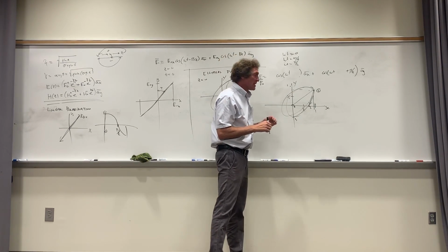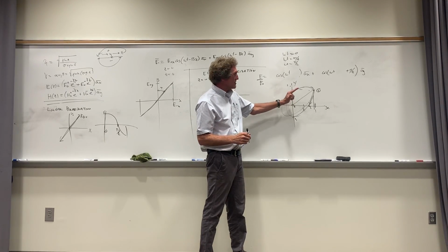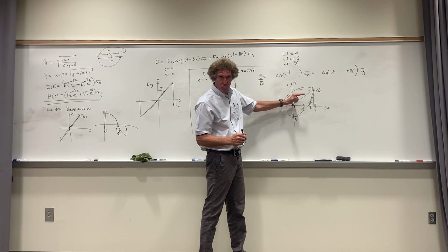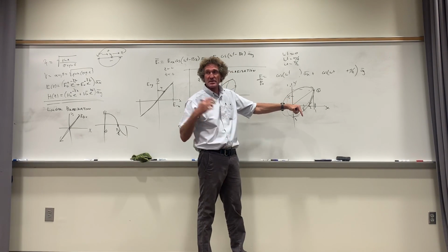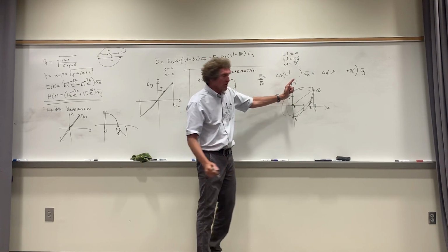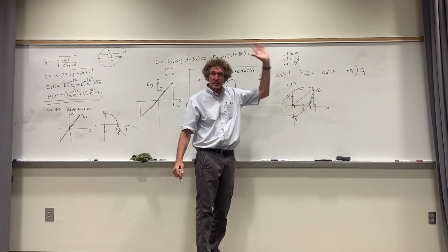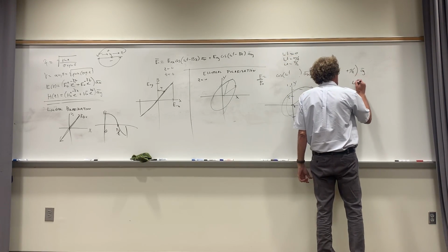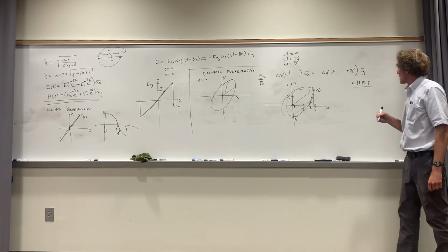But if you take your left hand and put it in the direction of propagation, and your index finger is in the direction of the tip of that vector, and it's winding in the proper way, or towards you like closing a door, then that's left hand polarization. Now this is elliptical. Which way is it going? Isn't it left hand polarization? How many see it's left hand elliptical polarization? So you would label this left hand elliptical polarization, or LHEP.